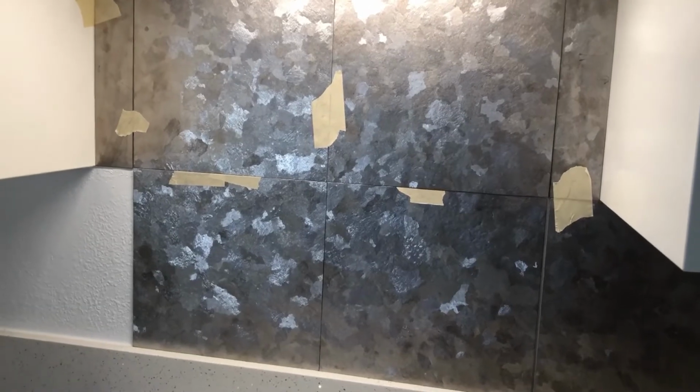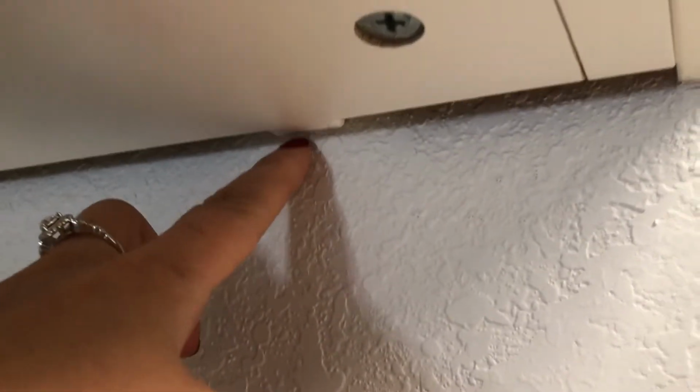So what we've done now is we have fitted up the drywall sheets to the wall, and we just used some masking tape to hold it in place temporarily. But what we found is that 2 sheets actually can't fit in this gap. And the reason is that when the cabinet was installed, there is a piece of plastic which holds the cabinet up to the wall, and that is just blocking the sheets from sliding in this gap here, which is very unfortunate.